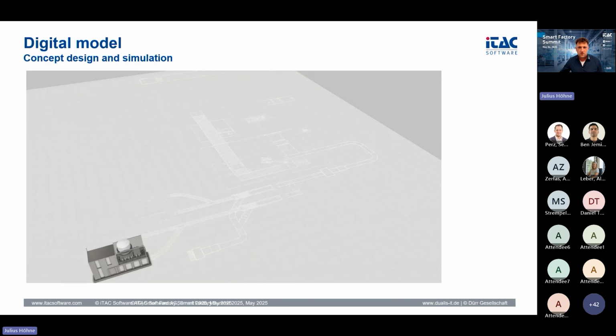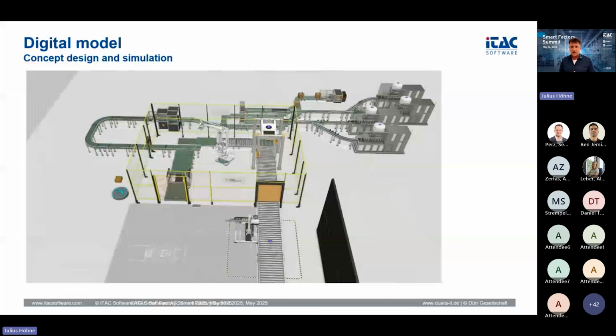So in this video, you can see how to create a digital model. We just placed the machines and the conveyors in the 3D world. And that is one benefit of a program like Visual Components. It has an e-catalog which includes nearly 4,000 items, such as machines, conveyors, robots, safety fences, industrial trucks, human workers or AGVs, and much more. And you just need to place the items in the 3D world, and the connection between the individual components, like from one conveyor to the next, happens automatically.